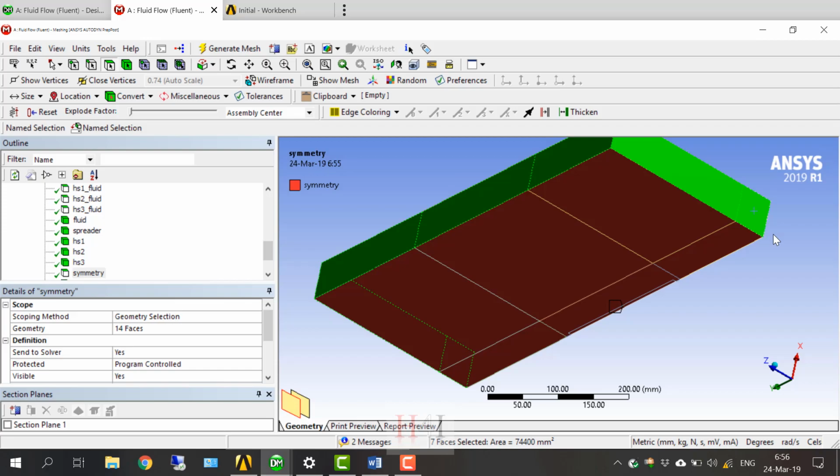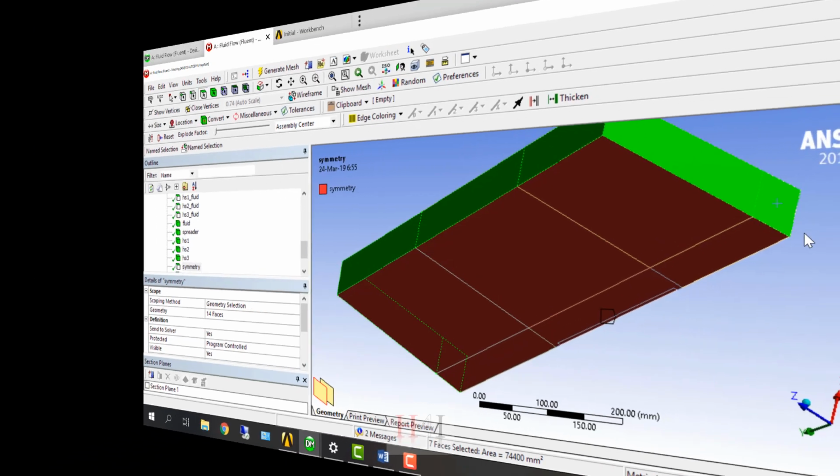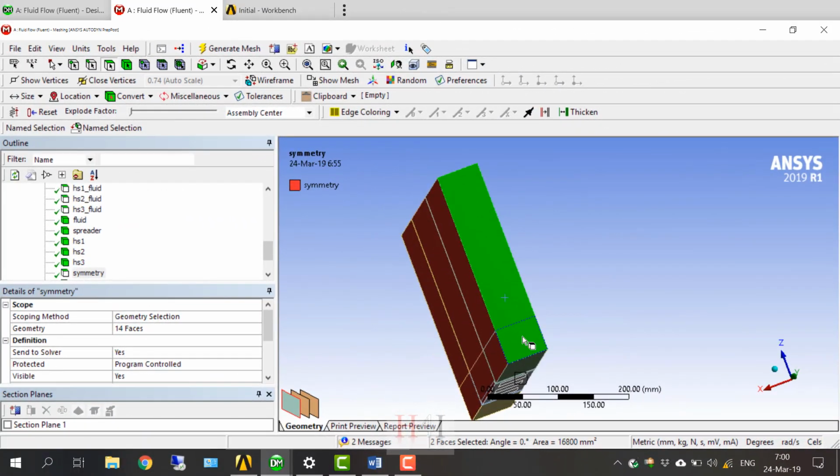If the flow is going inside during solving, it will assign the total pressure as the ambient pressure. If during solving the flow is going outside, it will assign the static pressure equal to the ambient pressure. I'm trying to explain it in the physical meaning, not because Fluent says so. When the flow is going outside, like from a water table, the flow adjusts itself so that its static pressure equals the ambient pressure.